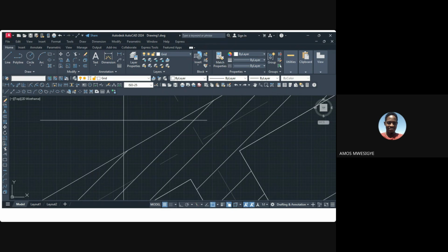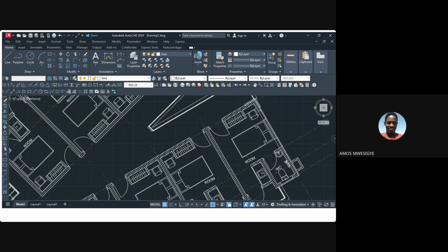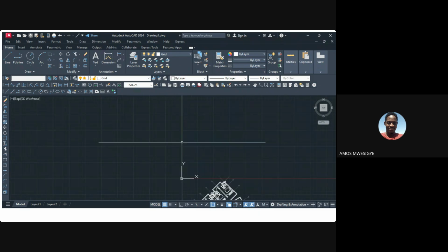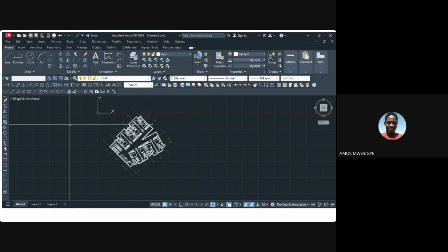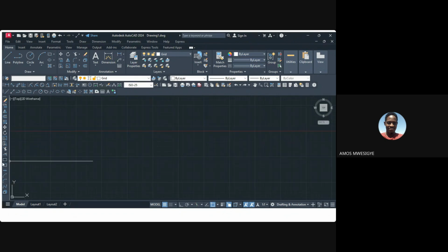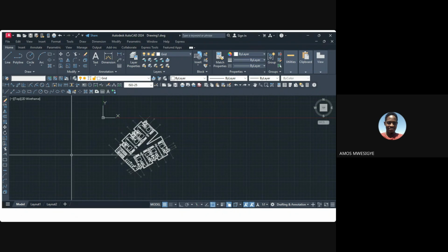So if I come here, remember I'm measuring. If I come here, I go to this end. This shows end point. If I select that end point, but I want the perpendicular to that because I'm measuring really the perpendicular distance from here to here. So you see, perpendicular shows you. So you select. You see, we are getting 199.8, which is really close to 200. So we can work with this drawing. So this is our clean drawing where we're going to put our map details.